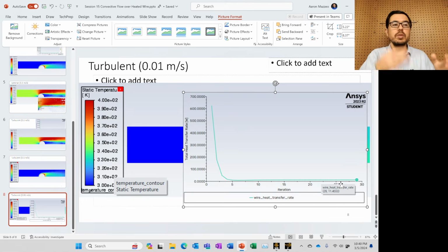If I want to use the high velocity, and I can get the temperature of the air to be more or less the same, and even if it isn't, just having more flow, I'm able to expose a given area of material or solid to more air at a higher temperature, and that's going to lead to a higher heat transfer rate.